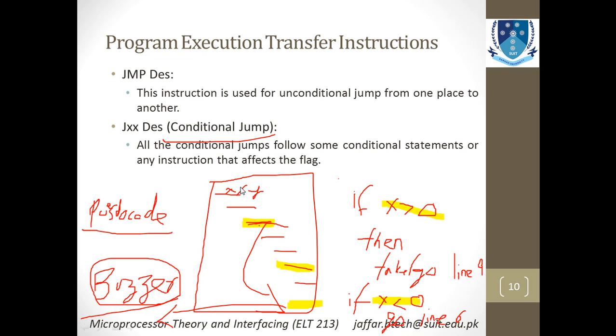You will keep looking at the bit to see if there is body heat or not. As soon as the body heat becomes greater than 0, let's say x is the body heat, it means there is some person in the building, so this will automatically jump to line number 9, and line number 9 is basically, let's say, set buzzer, and you know that set means enable the buzzer. So the buzzer will be automatically on